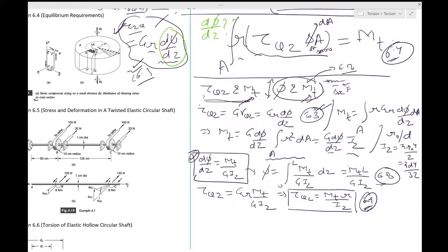The stress and strain distributions 6.2 and 6.3 on which these were based do in fact satisfy the fundamental equations of elasticity, so that for every small element the requirement of equilibrium, of geometric compatibility and Hooke's law is satisfied. So they all satisfy these conditions which were laid out in 2.1.